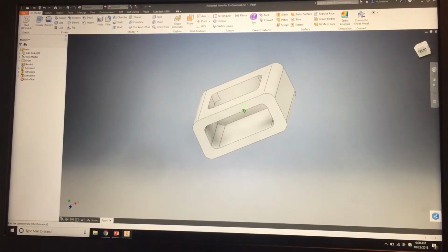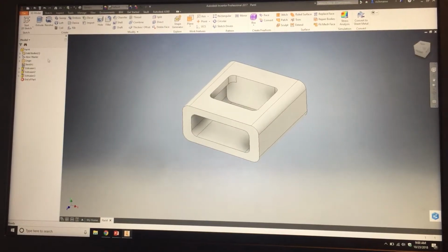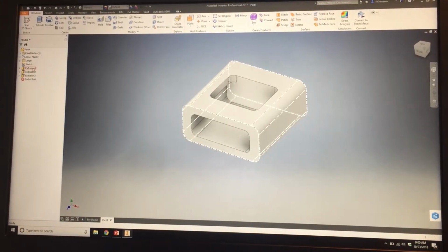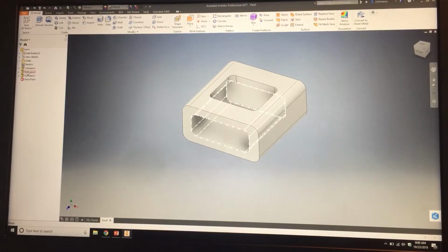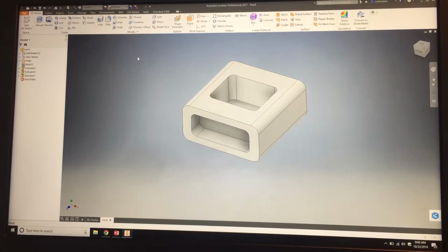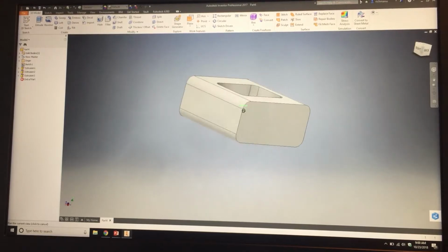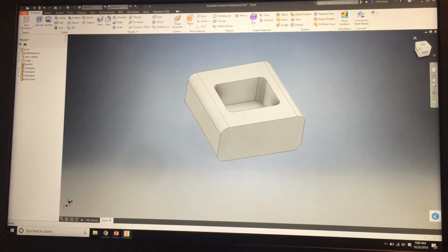What I would recommend is watch this. Let's go back to our original sketch. Okay. Not that one, this extrusion. We're going to double click on that, and instead we're only going to go 0.57 back. Okay, that's not enough either, right? So we need enough to cut through to that surface, right?